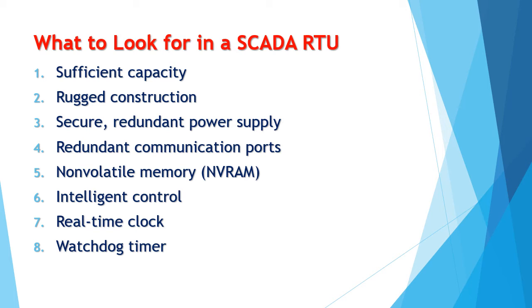Your RTU must have redundant communication ports. Network connectivity is as important to SCADA operations as a power supply. A second serial port or internal modem will keep your RTU online even if the LAN fails. Plus, RTUs with multiple communication ports easily support a LAN migration strategy.